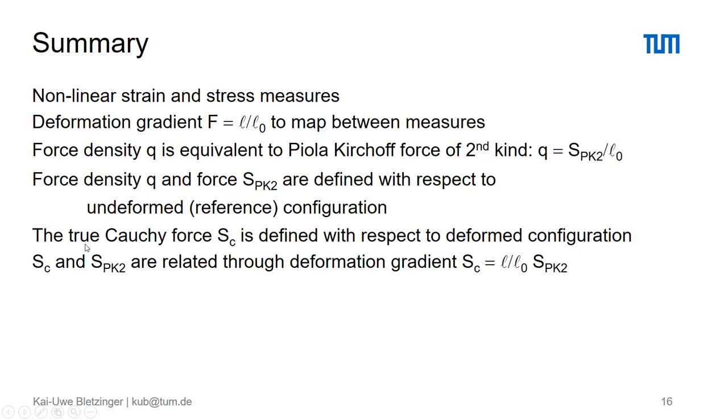We had introduced the understanding of what is the Cauchy force S sub C as what we call the true force. By the true force we mean the product of the true stress times the true cross-section. Remember that the true cross-section might be different from the initial cross-section by Poisson effects. And that means that the true force is of course related with respect to the deformed configuration. And then we have the two force measures, the Piola-Kirchhoff force of second kind related to the undeformed configuration, and the true force, the Cauchy force, and they just map by the deformation gradient.